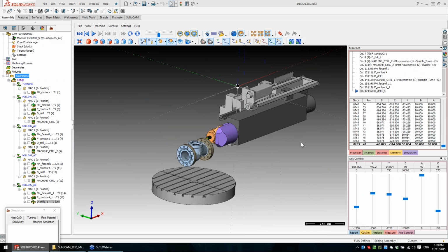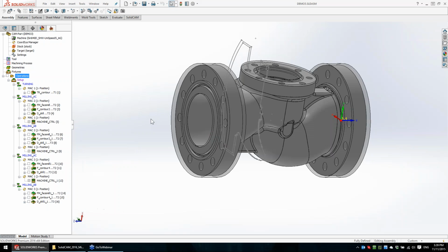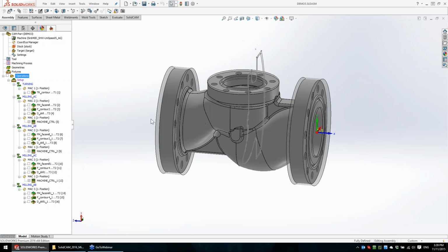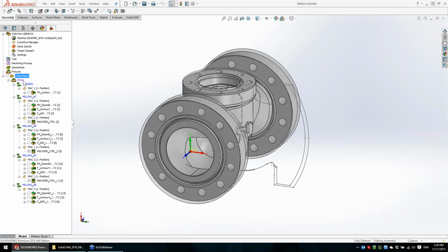So that's how we handle today the 6-axis machines, and this is how we move parts. We convert parts from one machine to another using the setup, creating a new coordinate system maybe, but all your program will be preserved, with nothing to edit, nothing to change there. Those are the subjects that I want to show you today.